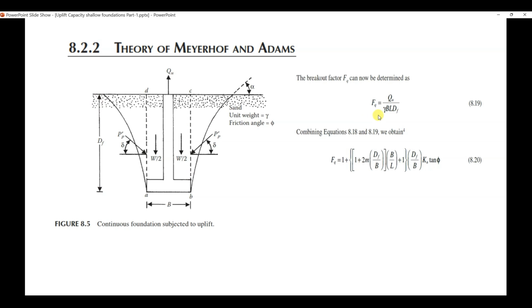In case of proposed foundation, you can use the existing foundation depth if you are not sure at which level finished ground level will be. And in case of existing foundations, you can go with the finished ground level, which is the plinth level of the ground floor.